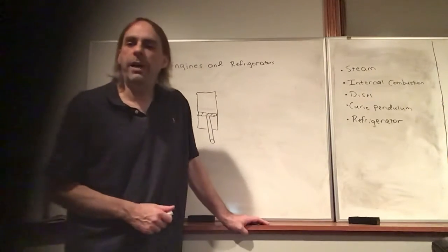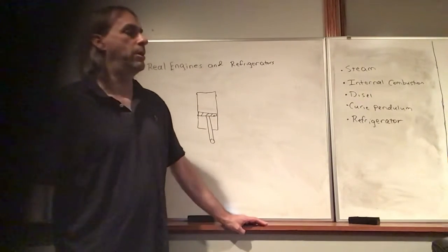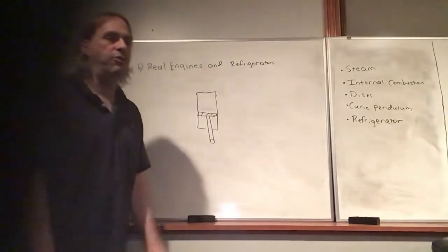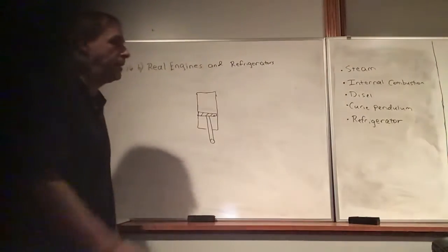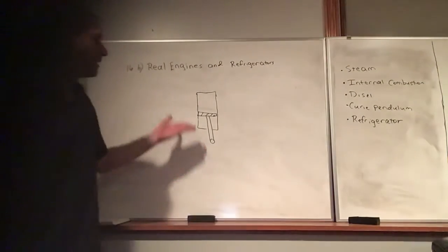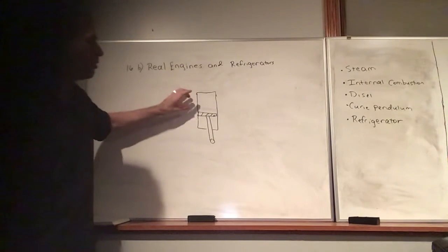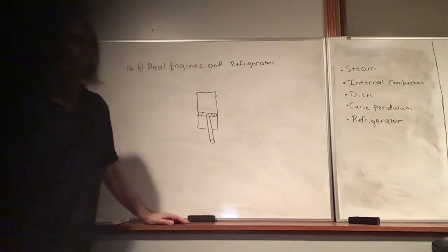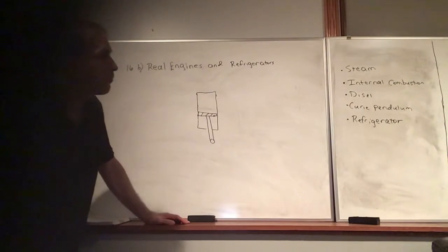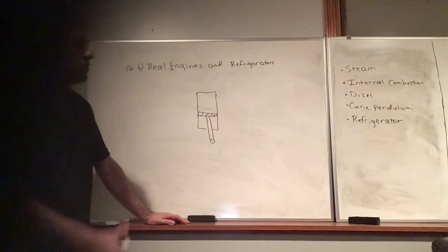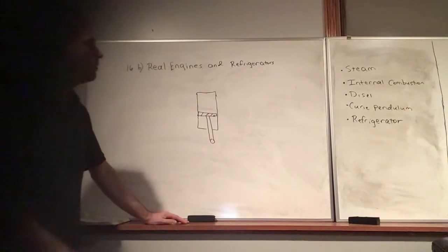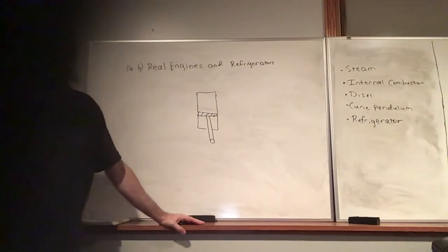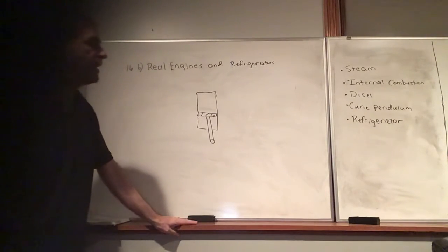However, they didn't go very fast, top speed. They accelerated very quickly, but when it came to high speed, even just a generic car, like a Kia, could maybe beat one in a high-speed race. And the reason is, at high speeds, the engine's working so hard, it's going up and down so fast, that there's not much time to get the fuel into the cylinder, so they have a kind of breathing problem. And so they lose a lot of efficiency at high speeds, whereas nowadays there's a fuel injector that actually injects the fuel into the cylinder, and so they can go much faster now.